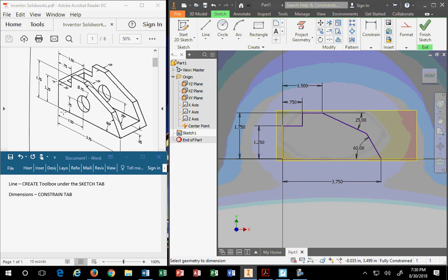This is literally their complaint. Why? Because I'm not teaching you properly. I'm supposed to tell you that dimensions have meaning. And when you put in dimensions that don't have meaning, they mess up the drawing. They mess up production. So you always make sure you fix these dimensions before you are done with your sketch, and make sure they reflect what they really need to be.